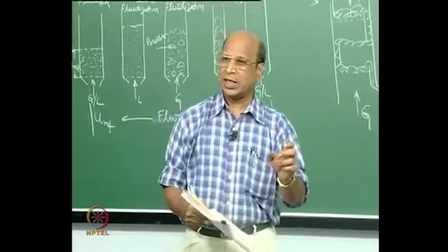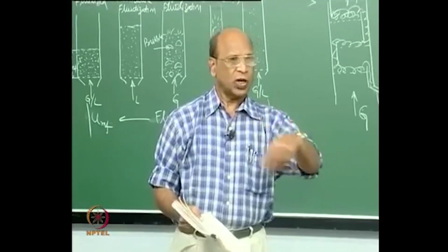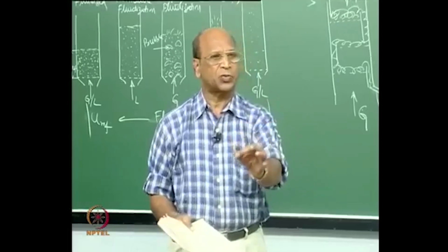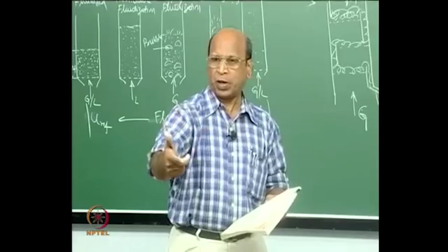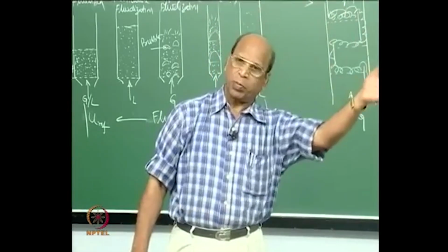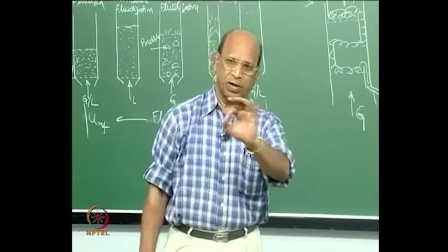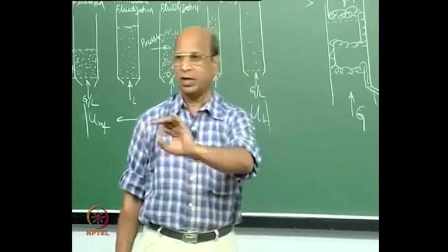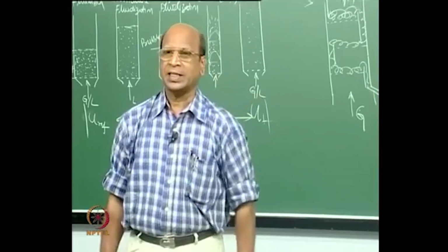Why is it a disadvantage? Because if I take coal combustion for example, solids are in perfect mixing condition. Because of mixing, some particles will come out very quickly, and practically the combustion in that particle is almost nil, and there may be another particle which is overburnt and then only ash is left. On the other hand, in a plug flow reactor, each and every particle would burn depending on the time which you have given, maybe 10 minutes or maybe 10 seconds, whatever.